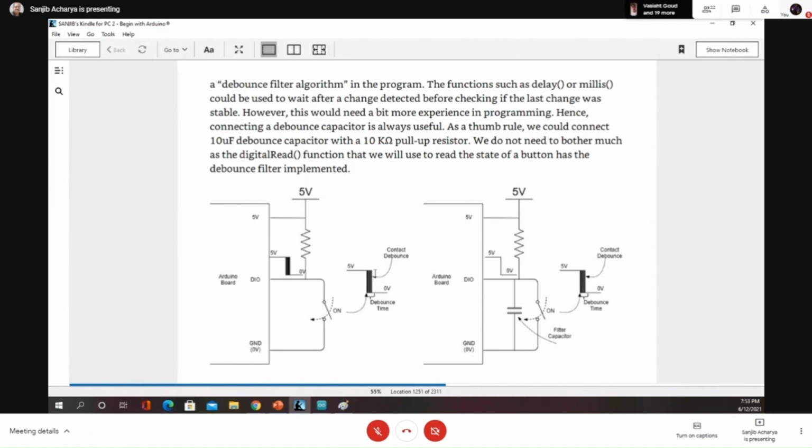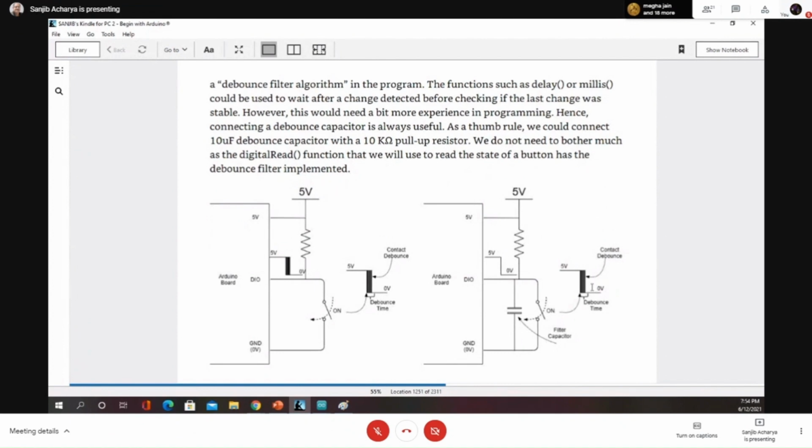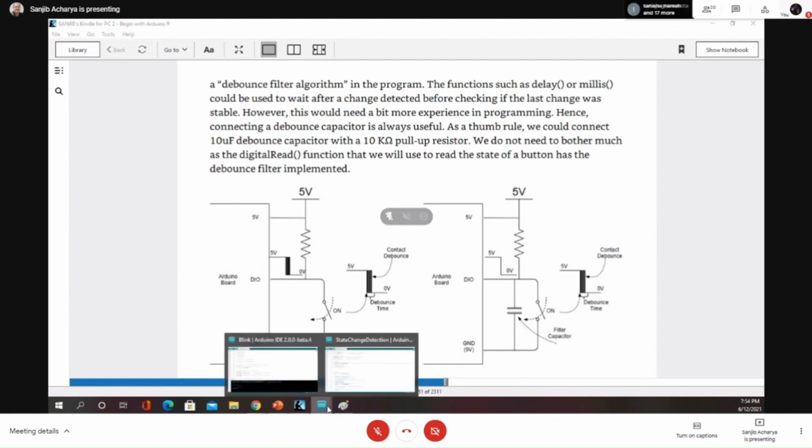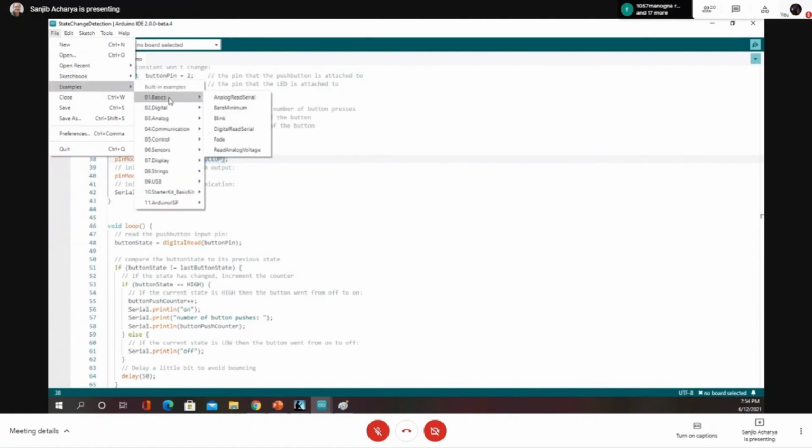So in order to filter that out, either you add a delay outside using a capacitor. So this resistor and capacitor will add some delay to the input, so basically your contact will debounce, but you will read a clean signal. It's a little delayed signal, but it will be clean. It will not be the same signal coming inside the microcontroller where you read all these transitions. So you will read a clean transition, or you develop a code which will filter out, which will add some delays in your code and filter out the contact debounce.